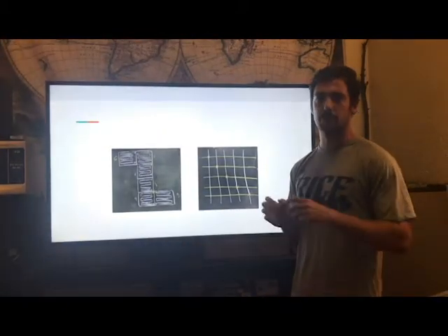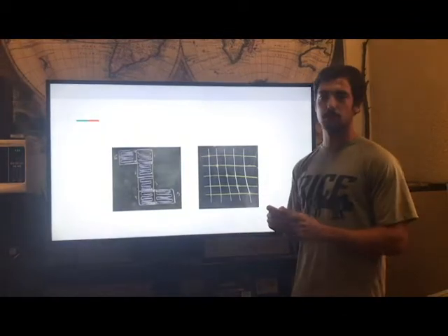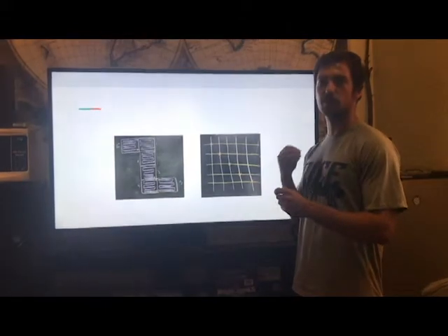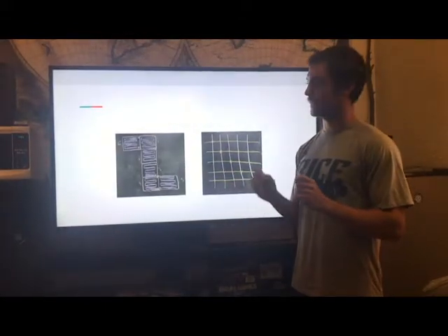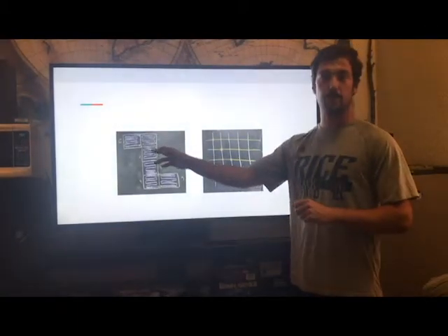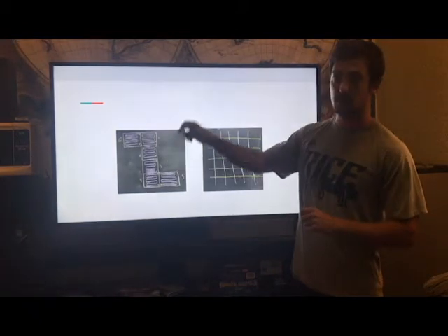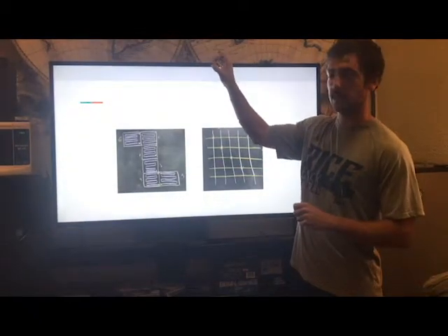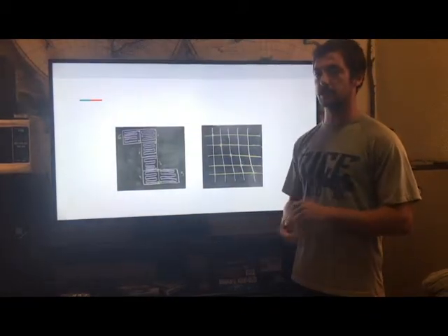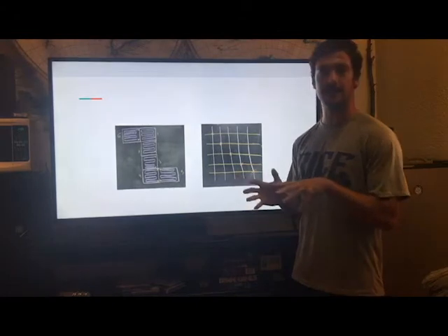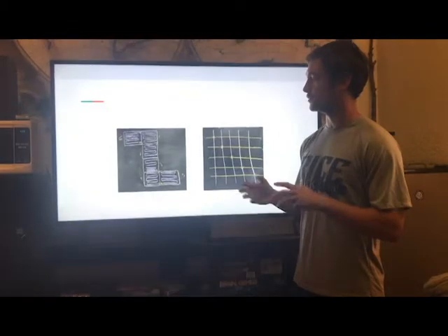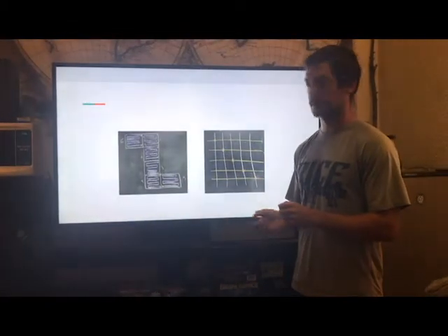When approaching how we wanted to format the array of LEDs on the cube, since we were using SPI communications, we were treating the LEDs as one single long chain. And to be able to map those into 3-dimensional space, we used a zigzag pattern per face, which would allow our first LED to be in the top right and our last LED for the face to be in the bottom right. This would allow for a short connection between the interfaces of 2 faces. And by flattening the cube into its net, we were able to plan out how we would want to arrange the faces next to each other, as shown.